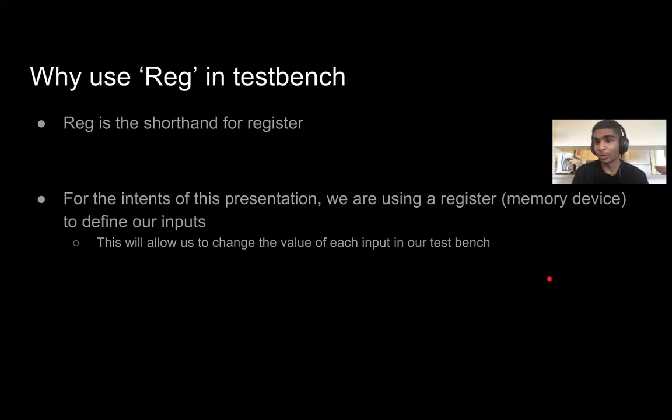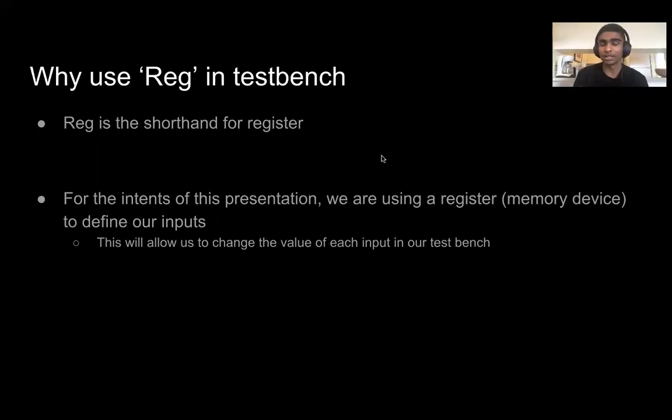And this is just a quick aside on the register. So register, or reg, is short for register. We are just using the register here as a memory device to define our inputs, and that allowed us to change the inputs and maintain those states during the test bench.